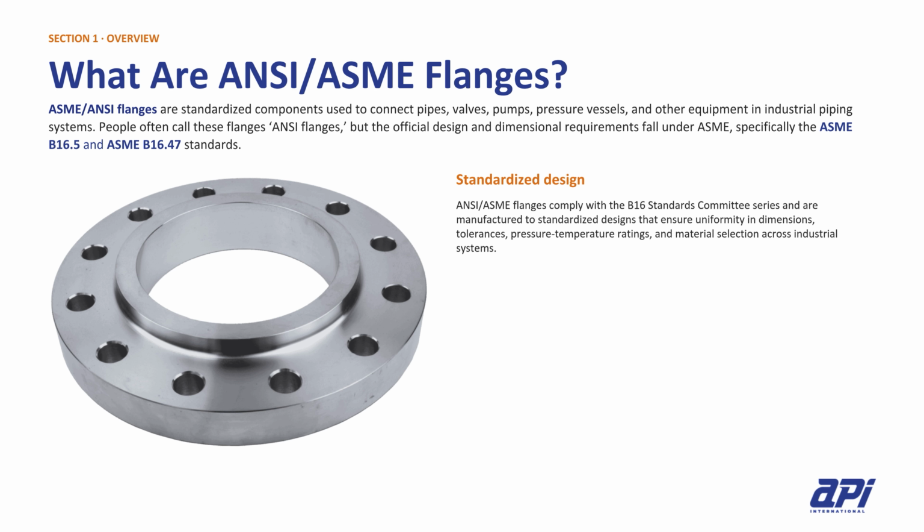ANSI and ASME flanges are standardized components used to connect pipes, valves, pumps, pressure vessels, and other equipment in industrial piping systems. They're often called ANSI flanges, but the official design and dimensional requirements fall under ASME, specifically the ANSI/ASME B16.5 and B16.47 standards. Because they follow the B16 Standards Committee series, their designs are standardized for uniformity in dimensions, tolerances, pressure temperature ratings, and material selection.